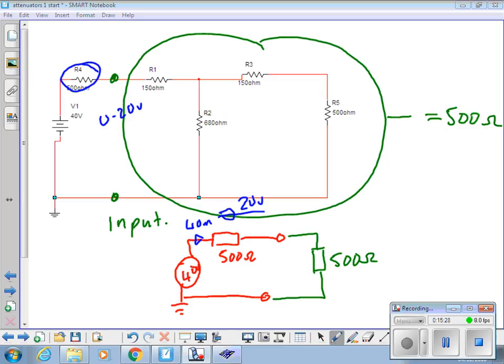Do you get that now, Carl? I get it, but if that's going from an instrument in the field, such as the pressure transducer, then it's supposed to give off 20 volts. Yeah, but that's what it'll give off when it's loaded. That's why it specifies what the impedance of it is, because if you measure the voltage when it's open circuit, you'll get a much higher voltage than when you put the load on it.